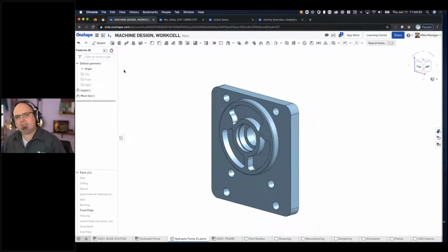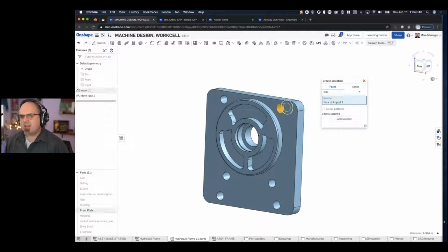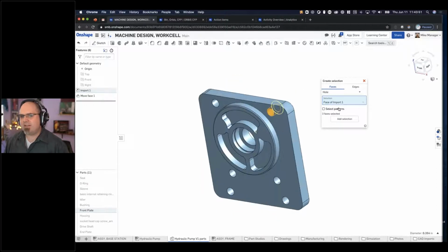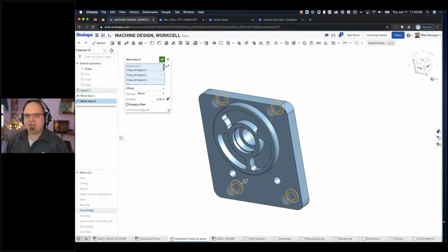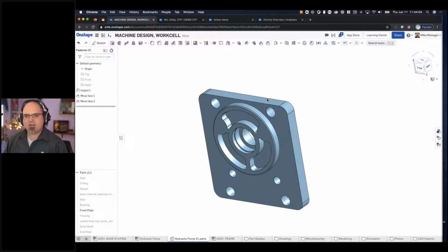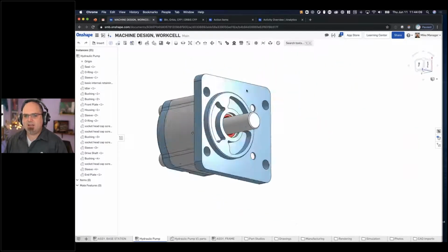So even though we imported a step file, I was able to make modifications to it because it's got automatic geometric feature recognition. It's not feature recognition like finding the features of the original model. It's looking for geometric manufacturing features. Like I can say I'm looking for a group of holes. I pick that, and it sees that that's a counterbore hole, and I can find the patterns of them, add that to a selection set, and even modify, you know, the size of these holes pretty quickly, bigger, smaller. We'll make these 0.05 bigger. And just like that, we have the new parts, and of course that's updated the assembly just like that.